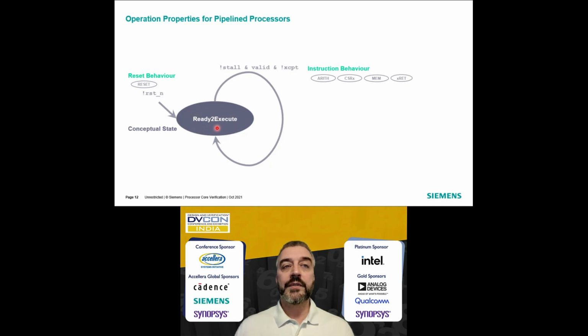And well, what then needs to happen for an instruction actually to be executed? There shouldn't be a stall. We need that there is actually something valid coming in from the fetch interface. So these two essentially mean there is something that is to be executed. And finally, the third part of the condition essentially says that our ISA model, so the formal model of the ISA, is predicting that no exception is supposed to occur for this particular instruction.